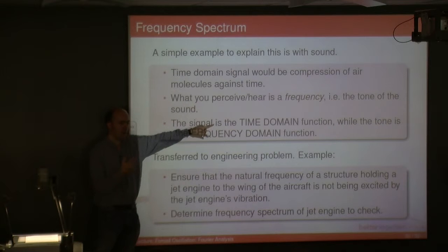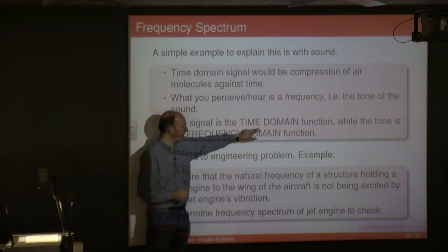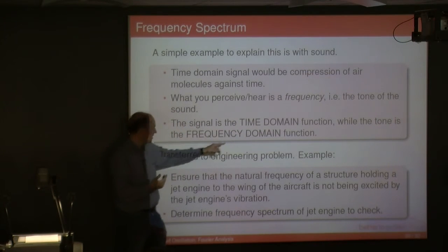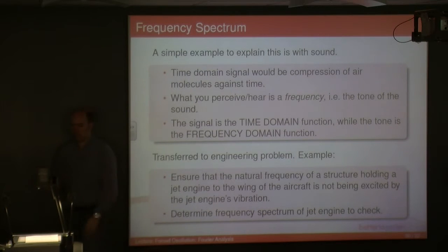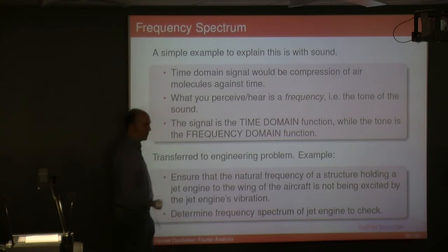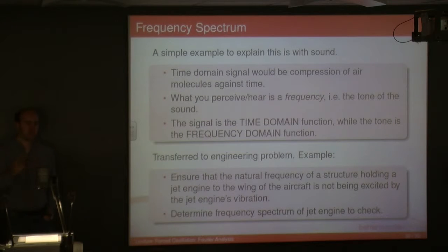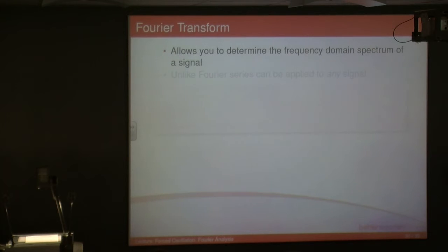You can shake it randomly and get a time domain response for its vibrations, and obviously then you can convert that to the frequency domain. Now, I've said quite flippantly, just convert it to the frequency domain. Obviously, that's fine if your time domain response is a periodic function. You can convert to the frequency domain just by taking the coefficients of your Fourier series. But often, that's not the case.